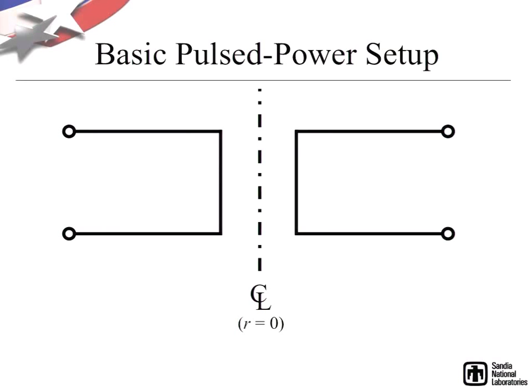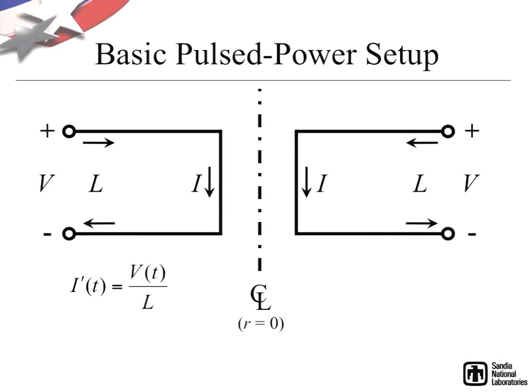line here, and then we can just take a metal cavity in a cylindrical geometry, right? And we can apply a voltage to it, and this cavity, due to its geometry, has some inductance associated with it. So from freshman physics, we know that the rate of rise of the current is going to be proportional to the voltage we apply divided by the inductance.